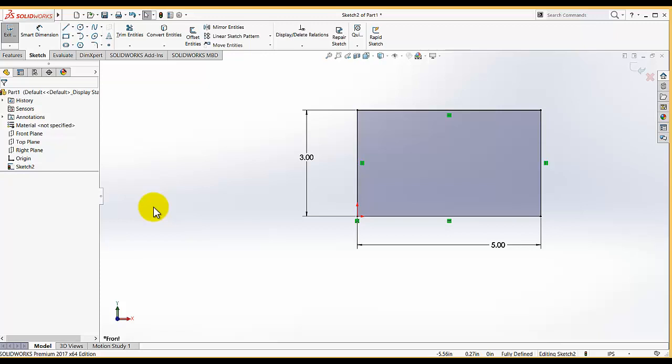The sketch will look good, it's very easy to change a dimension, and it makes the modeling easier for you if you fully define the sketch. Because by doing that you will also know the dimensions and relations of different lines and different types of sketch components.